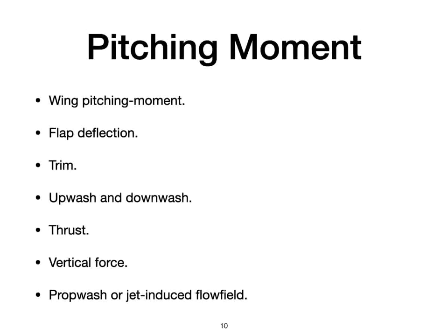A canard aircraft has a negative tail moment arm. The aircraft fuselage and nacelles produce pitching moments that are difficult to estimate without wind tunnel data. These moments are influenced by the upwash and downwash produced by the wing.